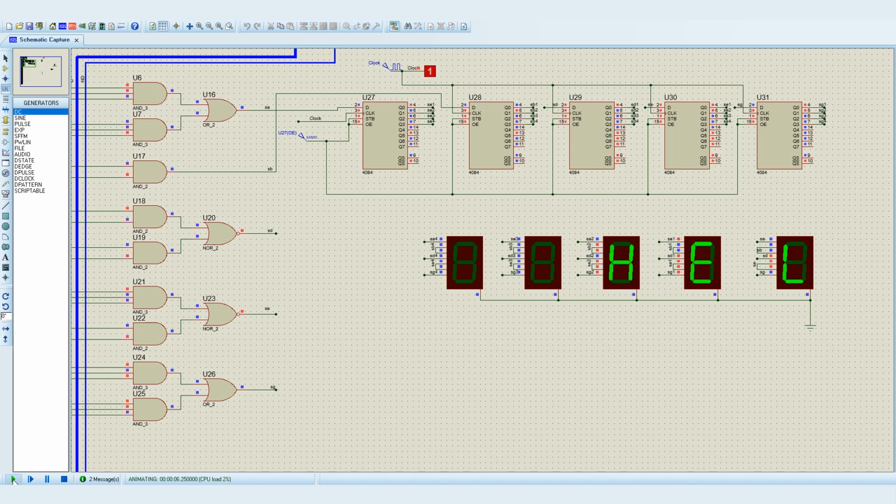That is pretty cool, to be honest. And you can change the message by changing the logic that we came up with here, but you wouldn't have to change everything with the shift registers. If you had 7 different Boolean expressions, one for each segment, then you'd need 2 more of these shift registers. But as it stands, we had a little bit of time saved because some of the outputs were identical. So that is pretty nifty.